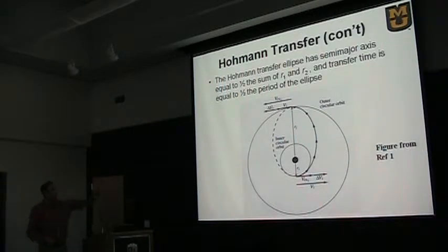The way it happens, just the picture is repeated. What happens is you calculate the first delta V as shown down at the bottom. You've got the circular speed of that small circle. And then I've got V1, that's the velocity I need to get on that ellipse. And it's greater because it's a larger orbit, and I have to be going faster. So the difference between those two arrows, that's delta V1. That's how much change in velocity that rocket has to produce for the first burn.